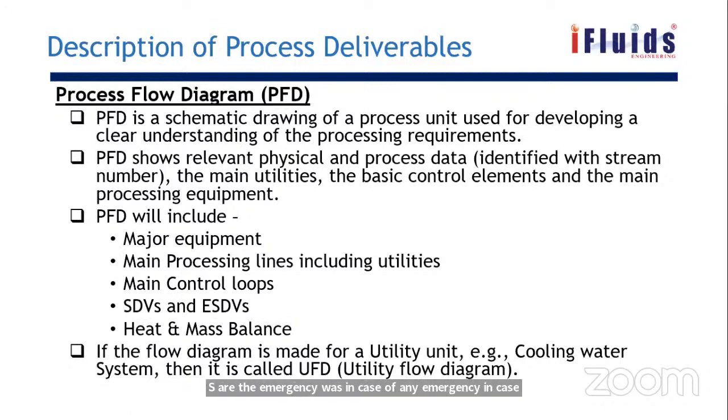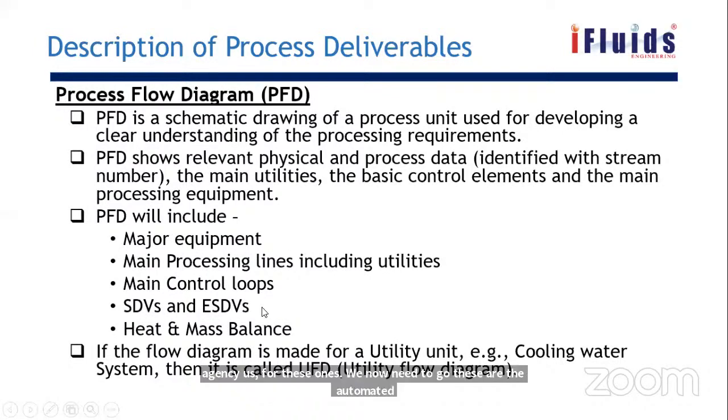So they can easily isolate the plant with the help of these ESDs, emergency valves. For these valves, we need not go. These are the automated valves. In case of any emergency, instruction is given to close the valves, and thereby they will be isolating the source.